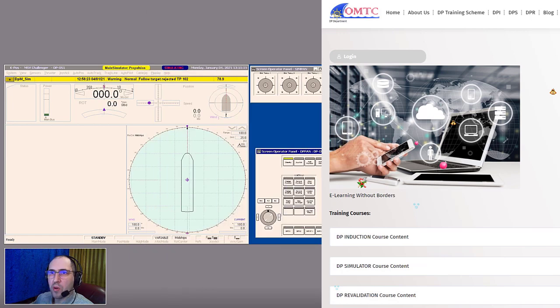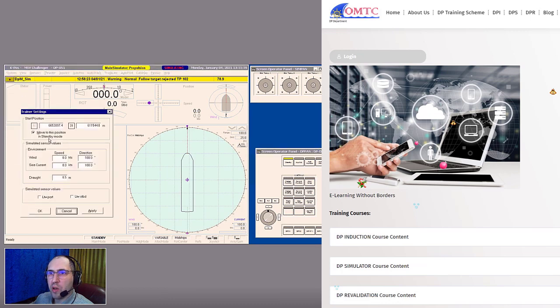Let's do that. We go to the system. Here we open the trainer. In the trainer, we are going to add the starting coordinate. It might be 665, 2900, and 611, 400. Ensure that the UTM zone, by the way, is 31.